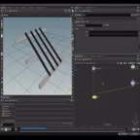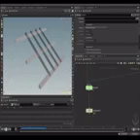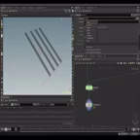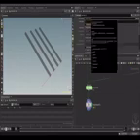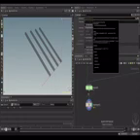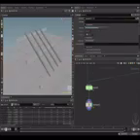Let's now import this simulation. And I'm going to do it by plugging here a .import node. And now I'm going to use the OP input path expression here. But this time I'm going to type OP input path parentheses, and I don't need to go two levels up. So this time I only need one point. And since we are calling the first input, we have to type 0 here. Let's close this. Let's set this to fetch geometry from DOP network.